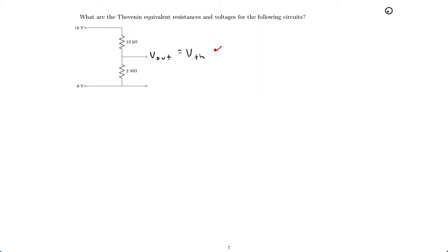And that's the first thing I'm going to calculate using the voltage divider equation, which is the lower resistor value, 2 mega ohm, over the sum of the two resistor values. So it's 2 mega ohm plus 12 kilo ohm. And that's going to be a number. Of course, this is times V in there. So that'll be V in times a number that's going to be pretty close to 1.